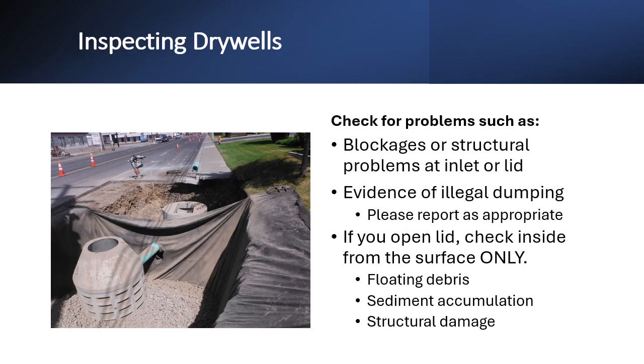Inspection of drywells should always be done from the surface. Check for blockages around the inlet from sediment, litter, or debris, or in winter, check for snow and ice that may be problematic. Check for structural problems at the inlet or drywell lid, including any damage, settling, or misalignment that could disrupt its function. Check for any evidence of illegal dumping. If you do see evidence of illegal dumping, please report this as appropriate.